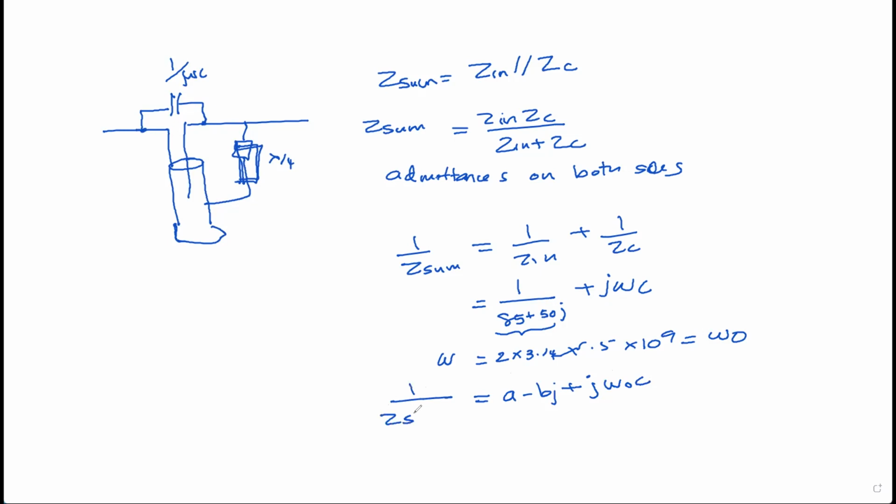In order for us to match the coaxial cable to the antenna, the final impedance at the feed point must be fully resistive. If there is some imaginary component to that impedance, that means the feed line is not connected to the dipole in a fully matched manner.